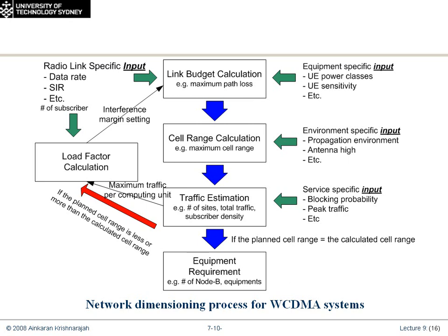So what will happen is your base station will be able to support the assumption of average traffic with a uniform distribution of subscribers. But when that peak occurs, obviously the base station can't deliver, so it goes into congestion. What you and I see as a consumer is a very slow packet data rate, and maybe even a blocked voice call as well in the worst scenario. So naturally we want to avoid that as well. So what we tend to do is we won't assume a uniform distribution of subscribers.